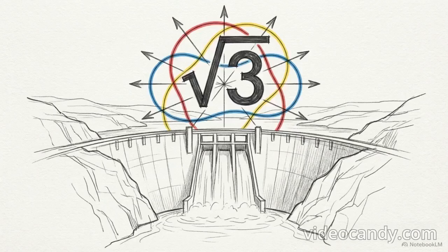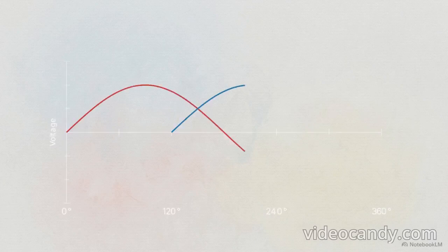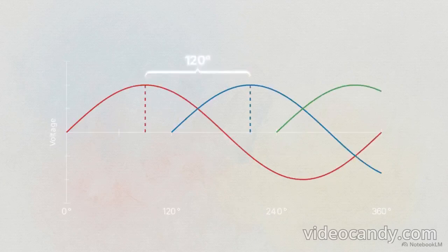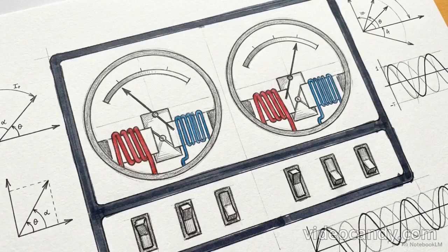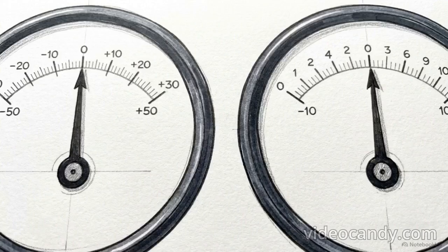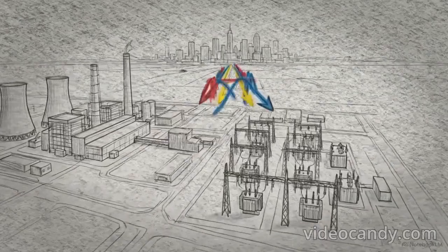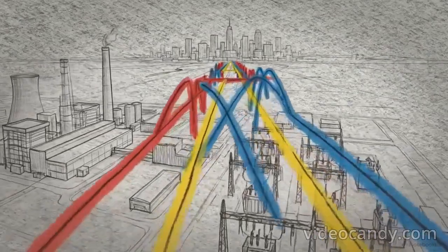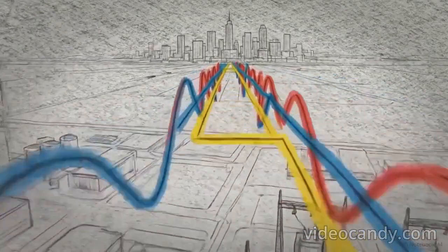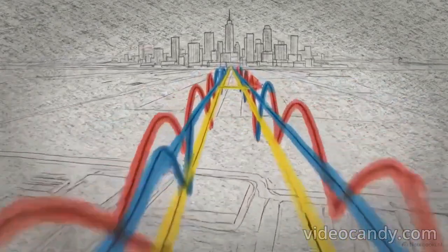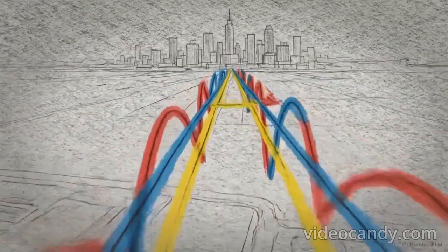The power factor is the ratio of actual working power used by a system to the apparent power flowing through it. 3-phase power operates as a perfect synergy of physical efficiency and mathematical elegance. The 120-degree offset between phases is the single underlying mechanism that reduces total wiring costs, powers self-starting heavy motors, and simplifies diagnostic measurement down to just 2 meters. By defining and maintaining the exact parameters of a balanced system, industrial power grids extract maximum mechanical output with a minimal physical footprint.